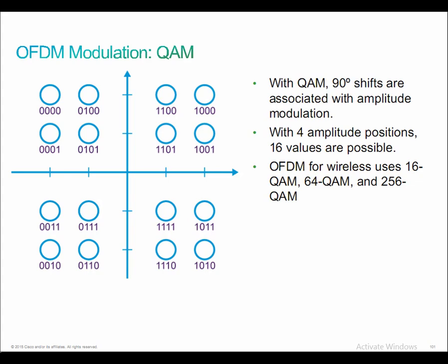In the case of digital QAM, we have a finite number of at least 2 phases and at least 2 amplitudes that are used. PSK modulators are often built using this QAM principle, but they're not actually considered QAM since the amplitude of the modulation carrier signal is constant in those scenarios.